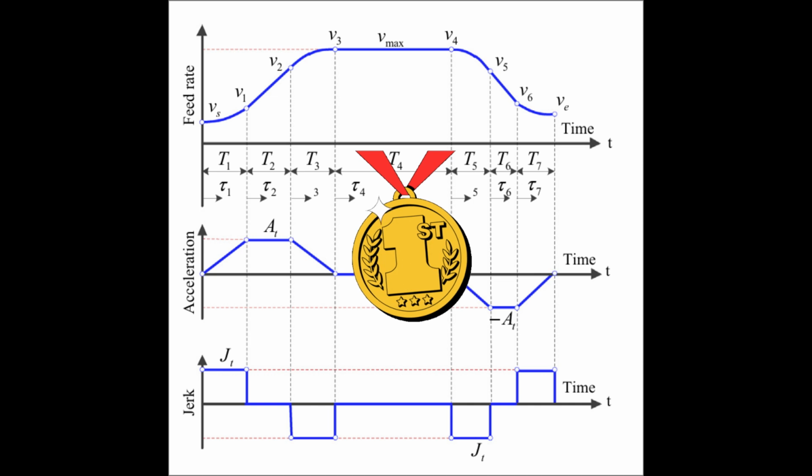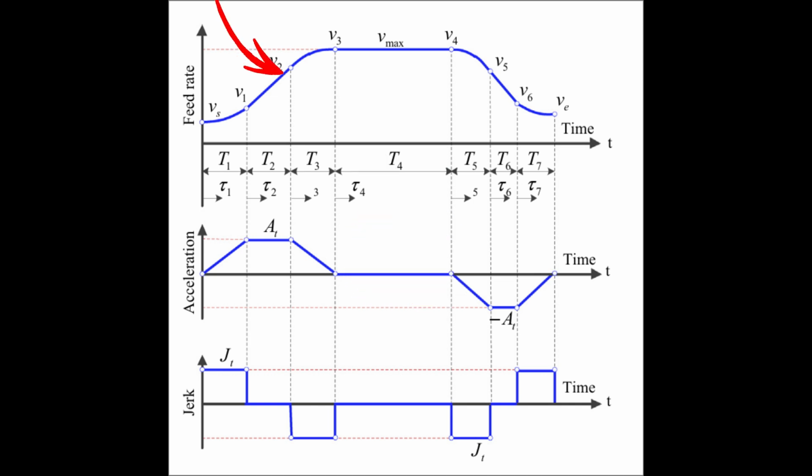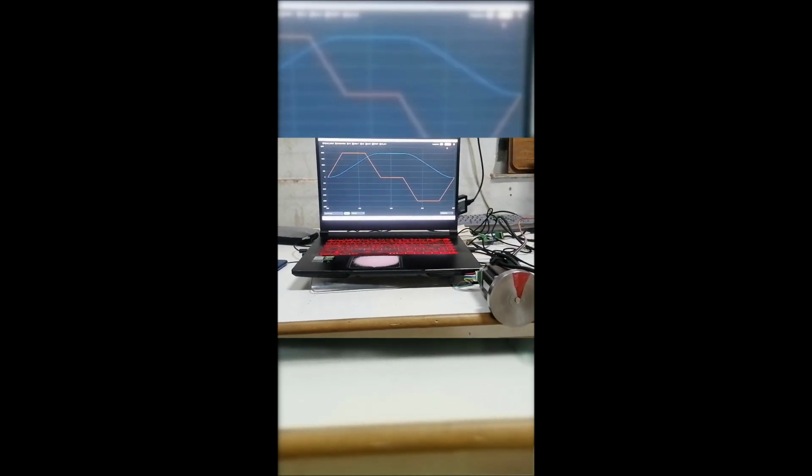And finally, our winning algorithm, the jerk-limited or S-curve profile. Notice how the velocity graph looks like a stretched letter S? In this method, we limit the rate of acceleration change. The jerk is no longer infinite, it is safely capped. This algorithm strikes the perfect balance. It makes the stepper motors run incredibly smooth and completely vibration-free. But because it uses linear polynomial equations, it's much faster, and our microcontroller can easily handle the math in real time.